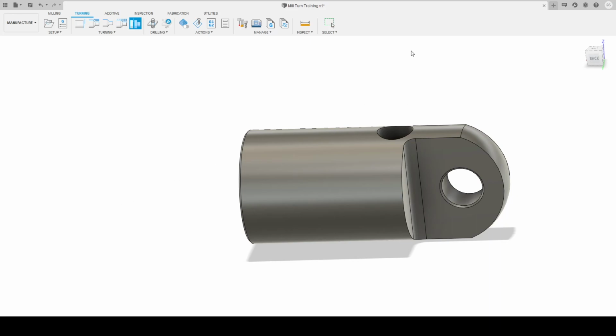The groove width is 3 millimeters. The corner radius is 0, and then the head length can be 5. Looks good. Holder, that's fine. Setup fine. Cutting data we'll get that off the packet afterwards, but something like for this we'll go a fixed speed of say 600 and 0.08, which will be pretty conservative.